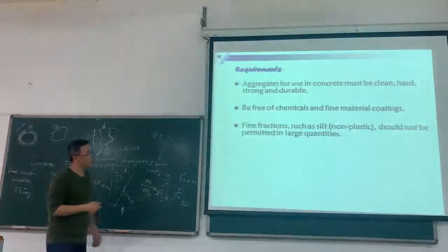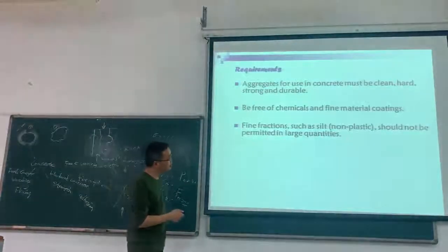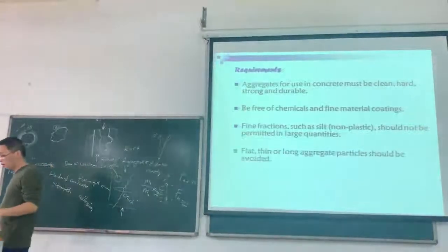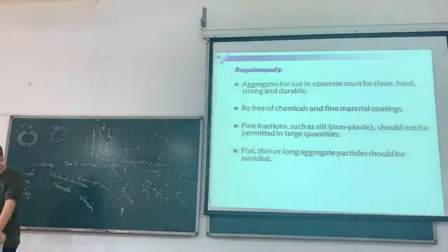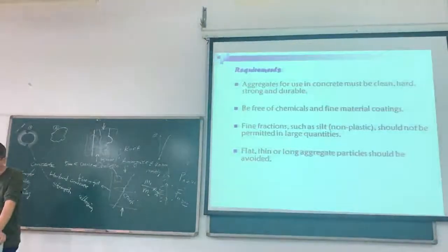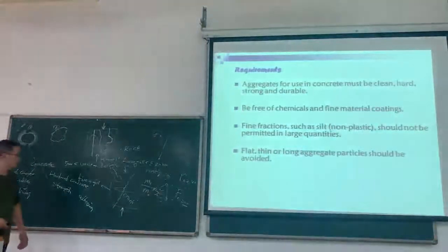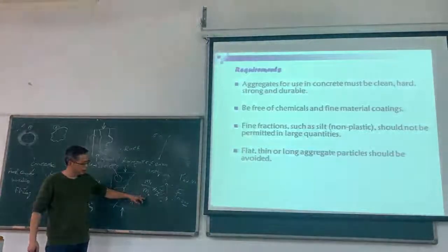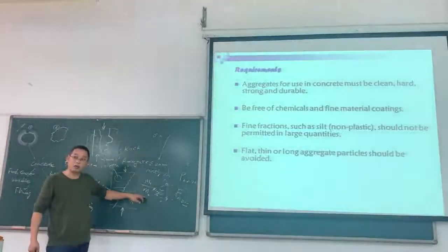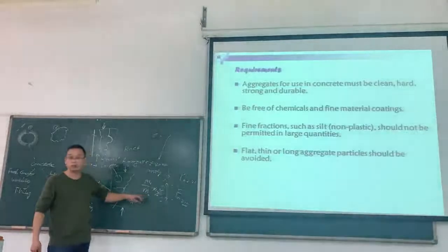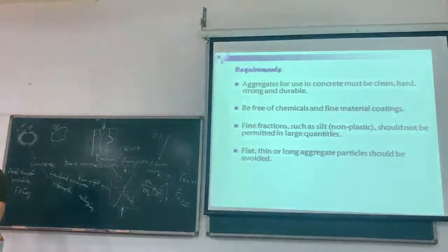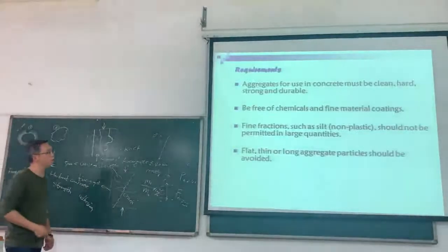And then the fine fractions should not be permitted in large quantities. And the flat, thin, or elongated aggregate particles should be avoided, just like this. The quantity of flat aggregate should be limited.